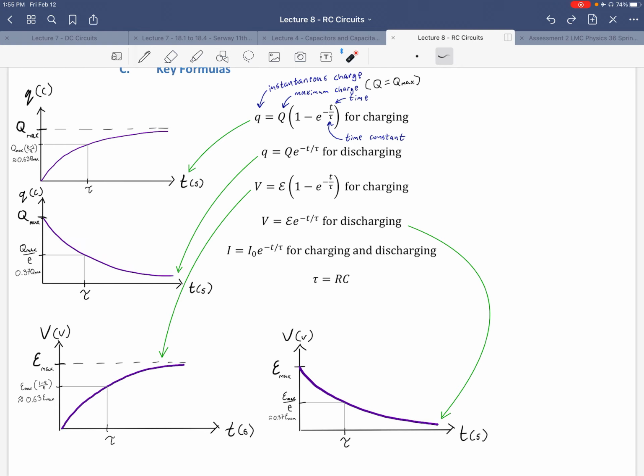So how do we interpret this in terms of the physical sense of the circuit? Well, what's happening as the capacitor is getting charged is it's building up a voltage to equal the voltage of the voltage source, the EMF, the battery. And once that capacitor is fully charged, say at some value of large t, much larger than tau, then the voltage across the capacitor is exactly equal to the EMF. And in that case, the capacitor is opposing the voltage of the EMF, and the current has completely stopped flowing, which I'll reiterate in just a moment.